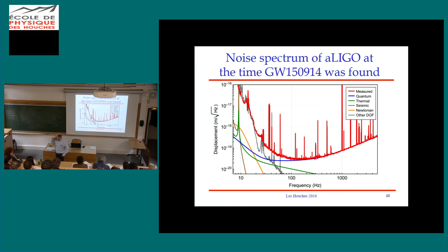Now, you would think, okay, it's not the mirror vibrating, but it's the things that are attached to the mirrors, and there's recoil, because when the middle of the fiber moves forward, the mirror has to move backwards. It's a big mass ratio, so you get a big dilution effect from the fact that the mirrors used to be 10, now 40 kilograms, and the mass of the fibers is pretty small, but it's enough to see. And it violates our design rule that we're supposed to put all resonances outside the signal band.